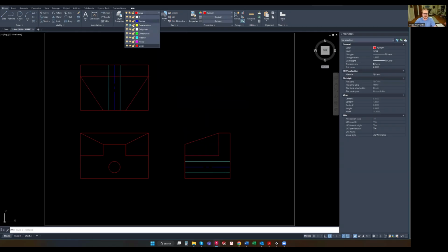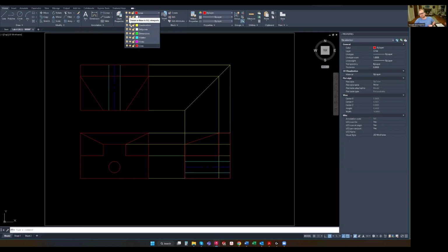I also would freeze stuff for when I used to do sheet metal design, like sheet metal patterns. So I would dimension my file for the CNC machine where all of the holes and stuff like that were. But then if you keep that layer on or not frozen, then the CNC router will actually try to cut those dimensions into the sheet metal.